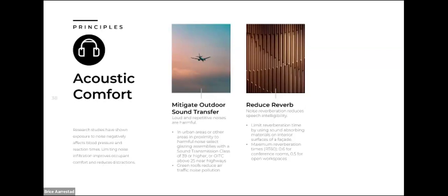And why this might be important for a facade, this could be something that occurs up at the transom level. You know, for acoustically treating a space, the highest bang for your buck is to treat the ceiling rather than the walls. So by placing sound absorbing materials up towards that ceiling, it's going to have a greater effect.